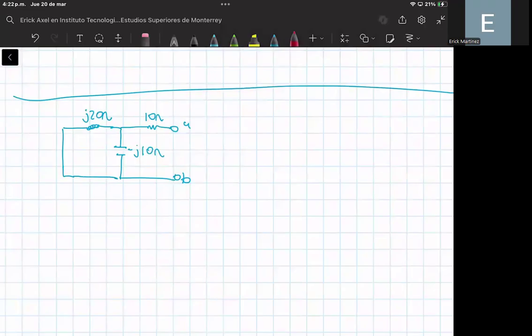And you can observe that, if you look closely into this circuit, and we need to compute the equivalent impedance between terminals A and B, we're going to compute ZTH, that is the equivalent impedance between these two terminals. Well, we can simplify the circuit as follows. First, you can notice that we have this inductor and this capacitor in parallel because they are sharing two nodes.